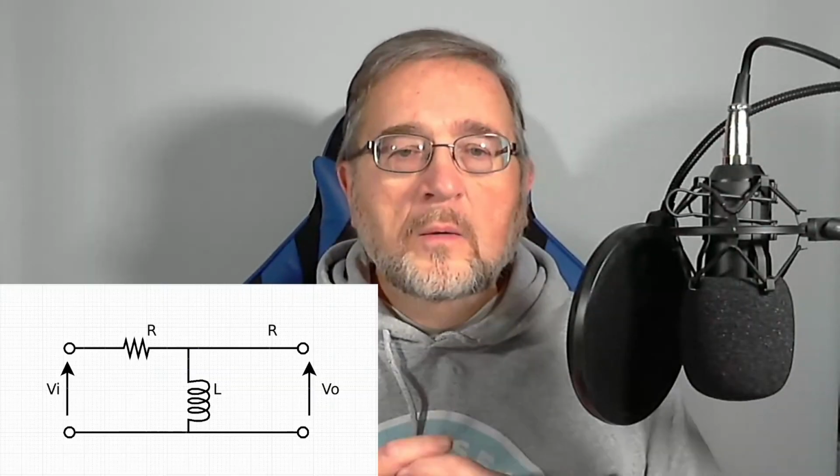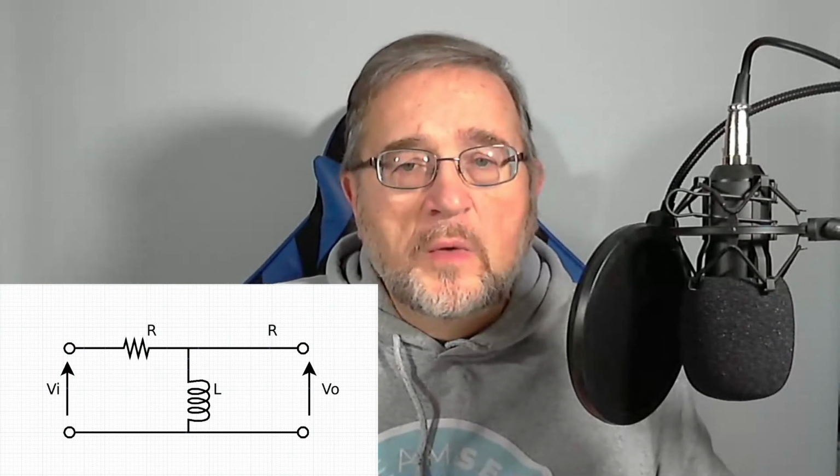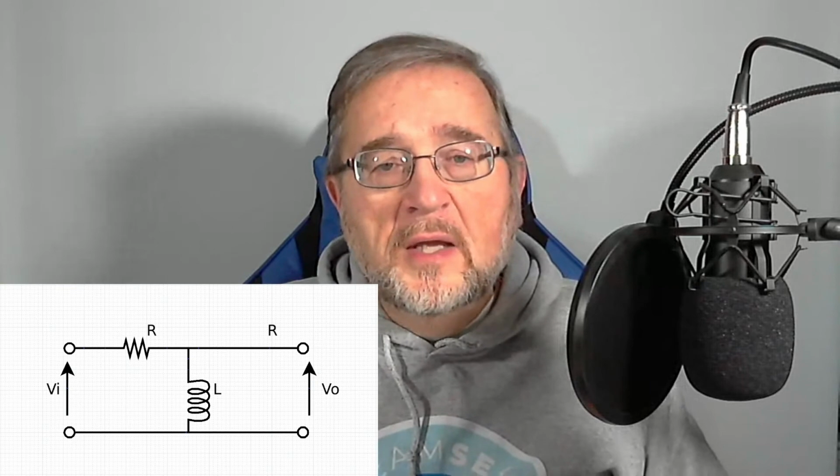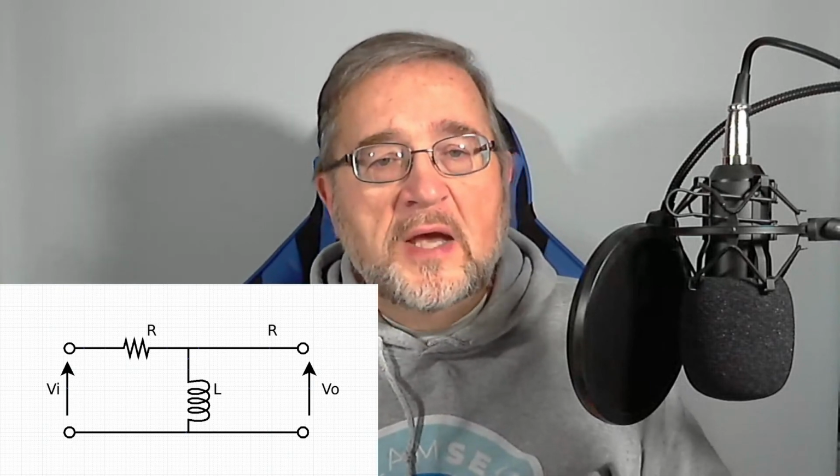Let's now take a look at another circuit and let's repeat the same process: the theory first, to identify the type of circuit, and the measurements second, to prove the veracity of the theory. We will analyze this circuit, where this time we have a resistor in series with input and output, and an inductor in parallel with the output. So let's draw here the new circuit now. The resistor, and then the inductor.